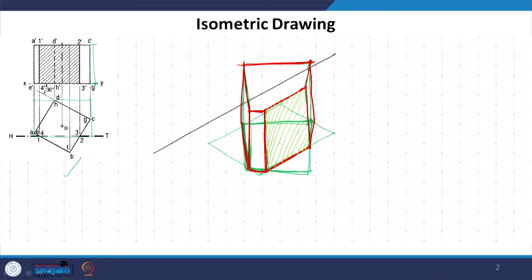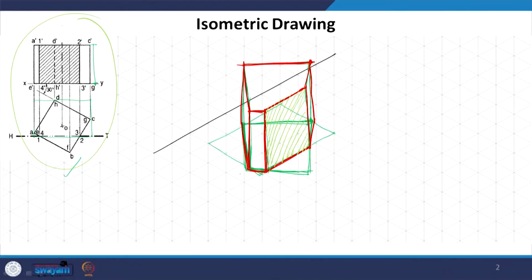It is actually quite simple, and if you look at this orthographic projection, this drawing, yes, this is required to arrive at this, but if I look at this drawing, I immediately get an idea, oh, this is a cube that is being cut. Here I have actually not drawn the remaining portion. Suppose we were to draw this remaining portion as well, like this, and make even these surfaces evident somehow. You would also see that this is how it is getting cut. I can extend this plane and also show that this is the section plane which is cutting.